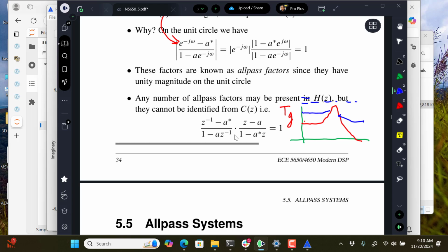And group delay is additive. When you cascade systems, you can't make group delay negative except under certain mathematical modeling concepts, which to me is still a mystery, but I'm not going to go down that path right now. So if you have to get rid of a blob of group delay that's some positive value, you can compensate by adding some all-pass sections in to bring this group delay up, so that it can manage that, and then bring it up here to make it flat in the passband.